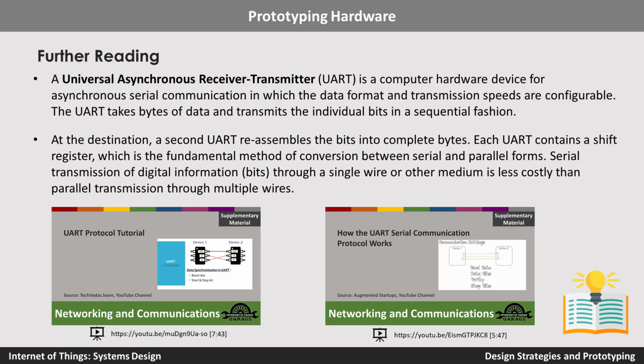You take a byte of data and transmit the individual bits in a sequential manner. So you send a sequence of bits, and then on the receiving end, they are put back together into a single byte. They are widely used in both Raspberry Pi or single board computers and microcontrollers in the Arduino domain. Typically, serial transmission of digital information as bits through a single wire is less costly than parallel transmission through multiple wires. That is why the UART is widely used, and we also call it serial ports.